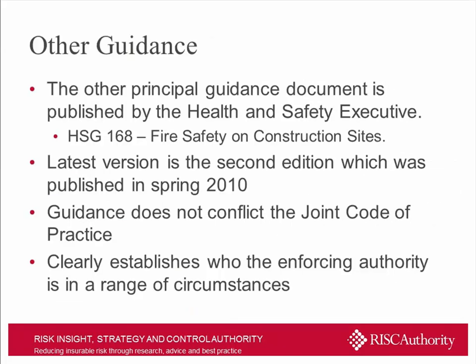Other guidance does exist. The Health and Safety Executive are the enforcing authority for construction works. Doesn't mean you don't have to do a fire risk assessment under the life safety legislation, as it were, the Regulatory Reform Fire Safety Order, which just covers general fire precautions. But the Health and Safety Executive are the enforcing authority, and they publish a guide, HSG 168, Fire Safety on Construction Sites.